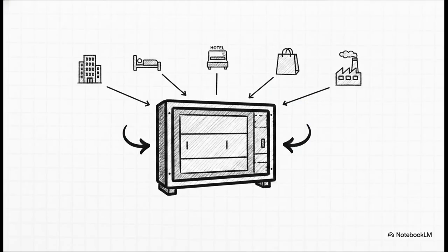Switchboards really hit the sweet spot. They give you an excellent balance of high capacity and practical economy. Plus, since they're freestanding, they can incorporate dedicated CT metering compartments. If you don't know, that's just a section built exactly to local utility specs where they measure your massive power consumption. This flexibility makes switchboards the absolute go-to standard choice for main service entrances in places like office buildings, hotels, retail centers, and light industrial facilities.